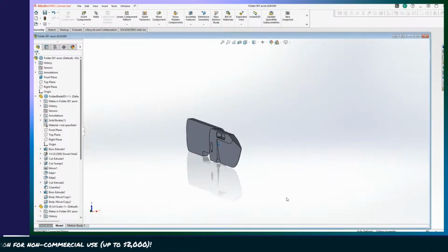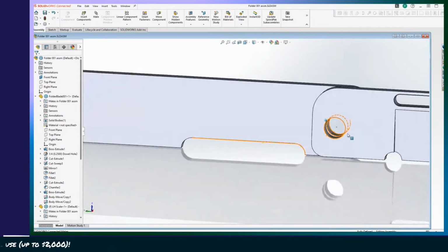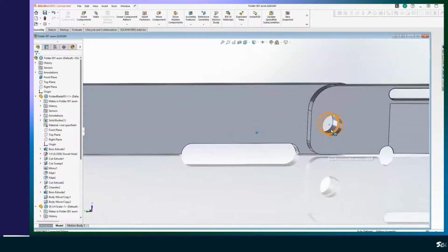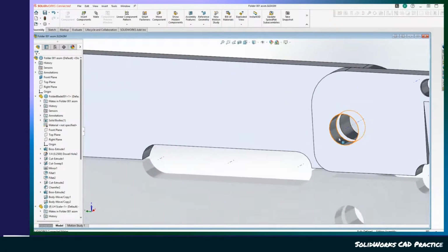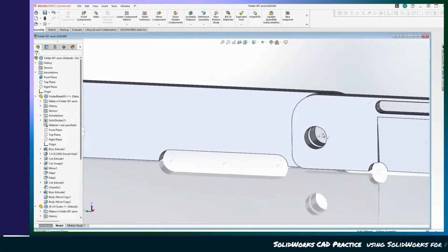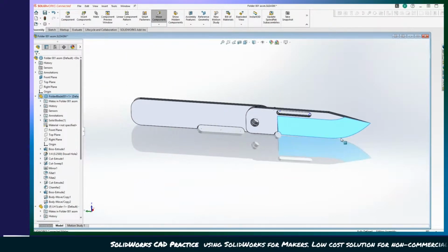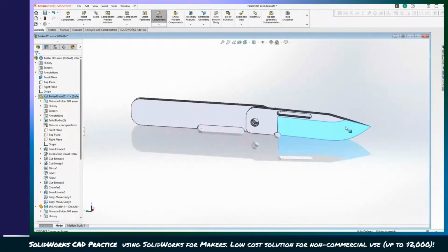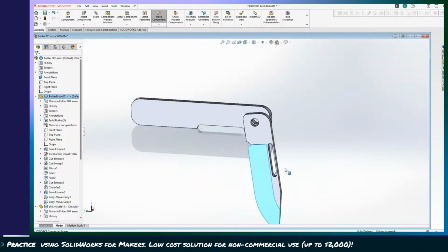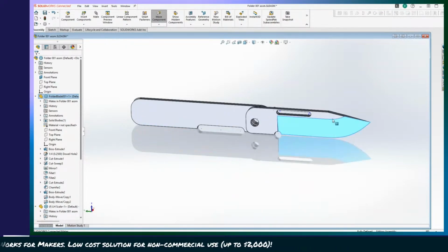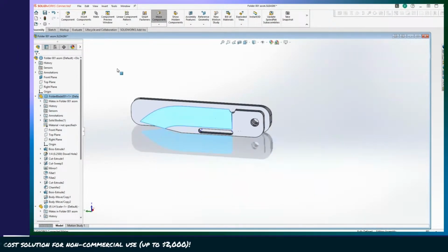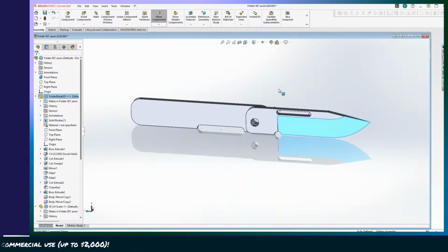If you're interested in the subject, we added some mating constraints on this axis, and then we did angle limits so that it won't go more than this far open or this far closed. So if you wanted to rewind, you could see how that was done. Or there's better videos on YouTube.